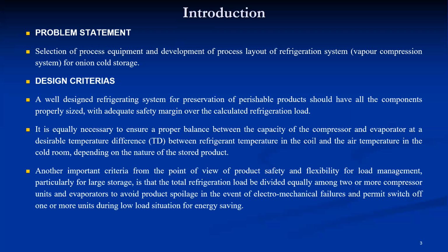Another important criterion, from the point of view of product safety and flexibility for load management, particularly for large storage, is that the total refrigeration load be divided equally among two or more compressor units and evaporators, to avoid product spoilage in the event of electromechanical failures and to permit switching off one or more units during low load situations for energy saving.